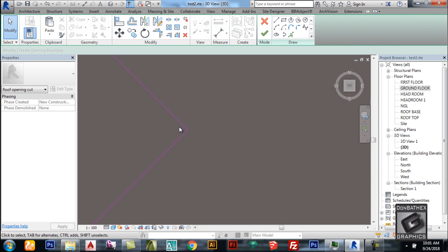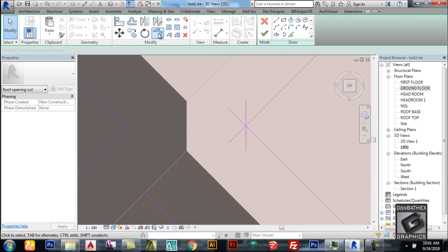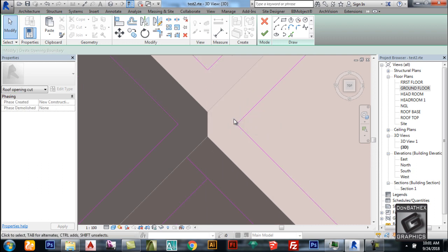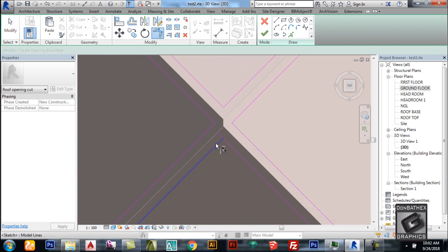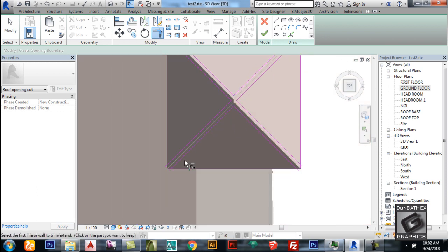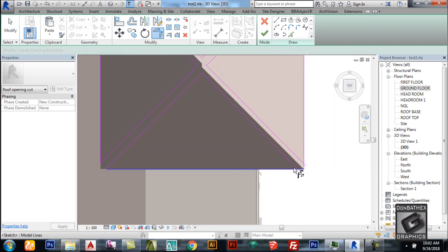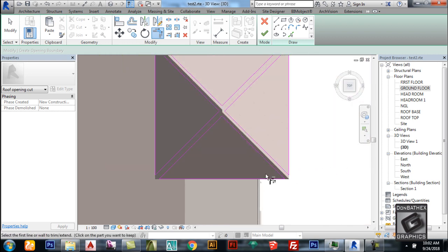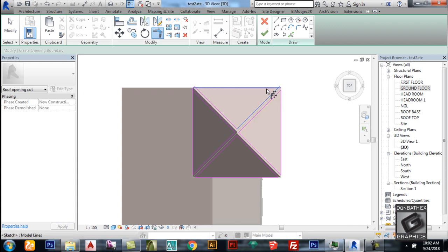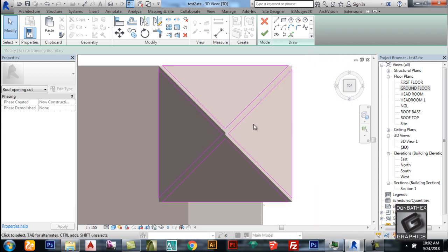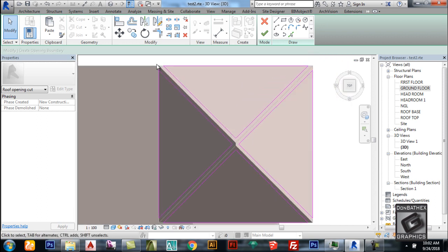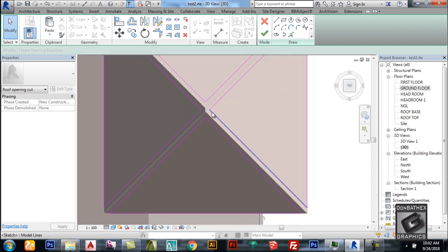And this is done. Same thing we'll do for here. Delete it, and trim this too. So the next thing we do is we trim this and this, this and this, this and this and this and this. What we did here is make sure that the parts that are open are actually going to be the parts left when we cut finish.